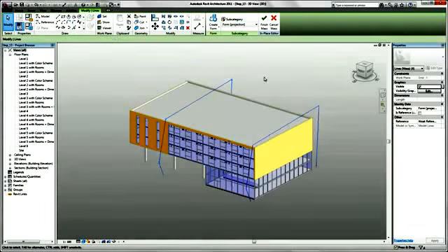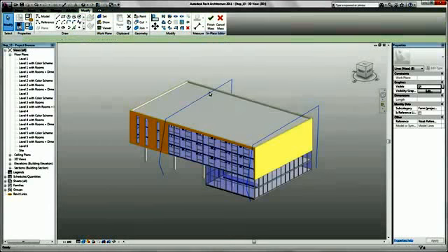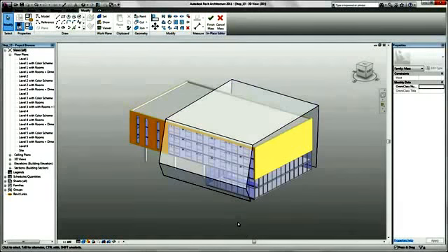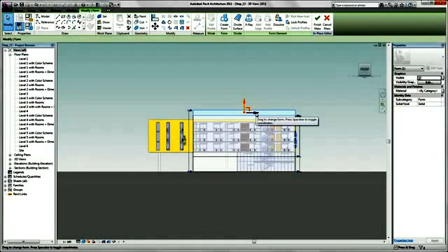Now we want to loft these two lines to create a surface. So we click both of them and click here on Create Form. So that's our first freeform. Now we can make several modifications. We switch in our front view. We can move a single surface,